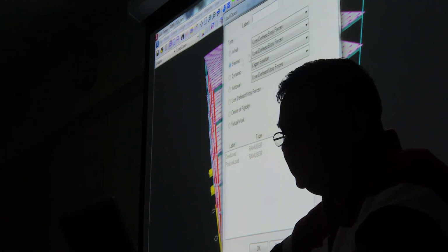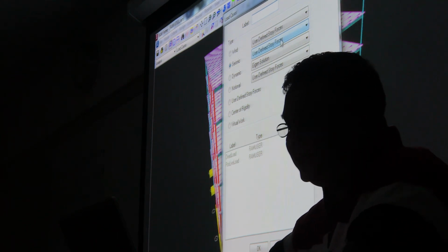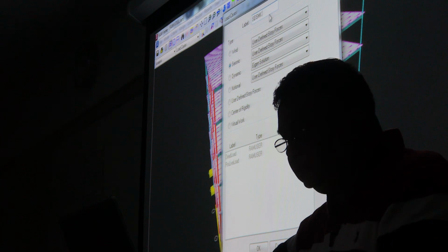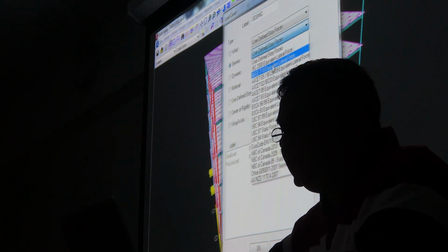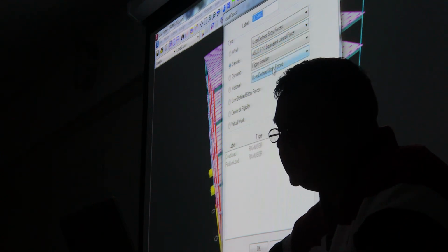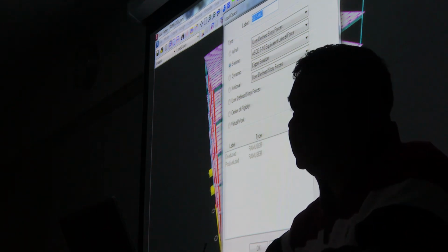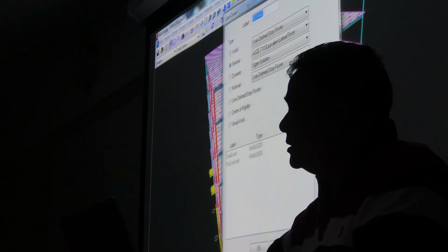Okay. So let's go with the seismic loading. Now you have to watch the video or picture very carefully because you don't know anything on that. Sorry for that. Seismic. And I'm going to use an equivalent lateral force method. Unfortunately, or fortunately, usually we should not be using it for a 6-story building. Equivalent lateral force method is not applicable anymore because you have to use a dynamic analysis. We are doing a static analysis.